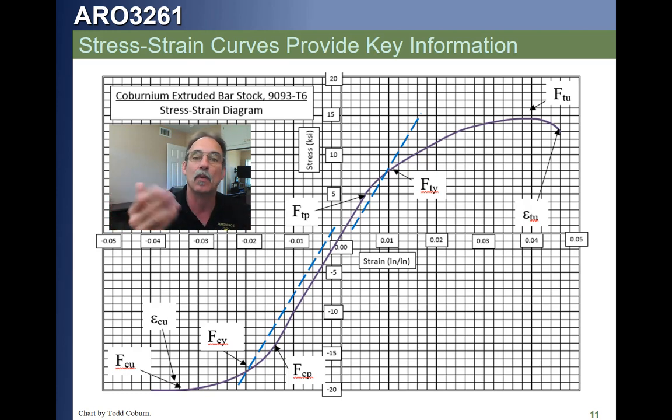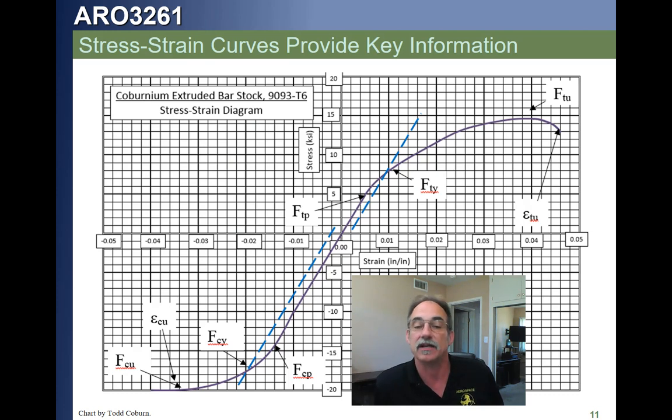And then we use subscripts to talk about what kind of stress. So you'll see FTY is the allowable stress. It's the yield stress in tension. Allowable stress, tension, yield. You see that? FTU is the allowable stress in tension, and it's the ultimate one, the most it can go to. Ultimate is a word that we use to talk about the very most. So the uppermost point of the curve defines the allowable of the material, the ultimate tension allowable FTU. If you look at the compression side, you see the ultimate compression allowable is FCU. F meaning capital allowable stress, C meaning compression, U meaning ultimate.